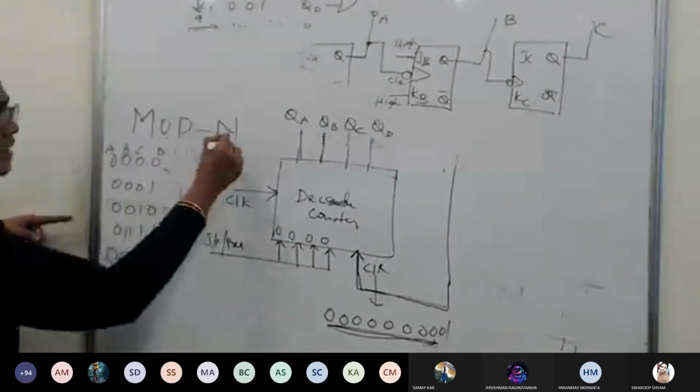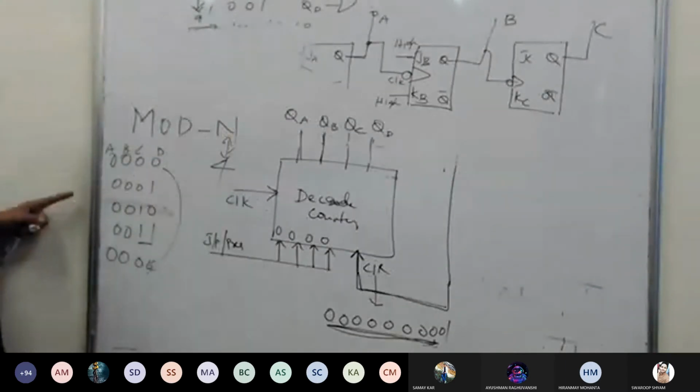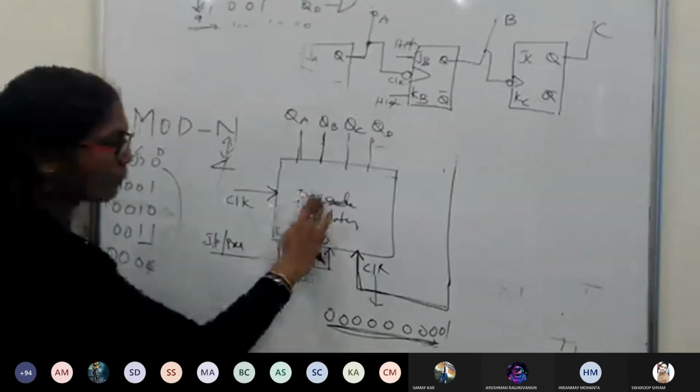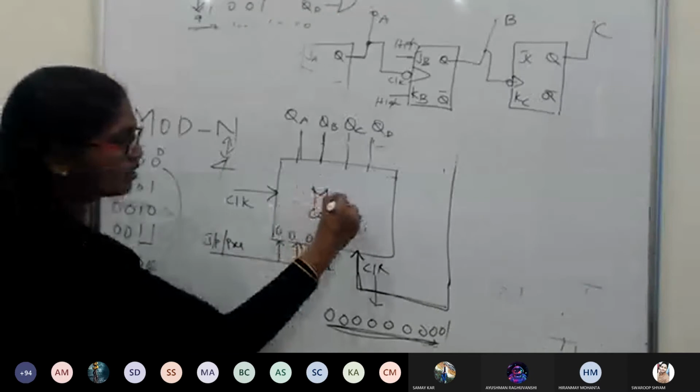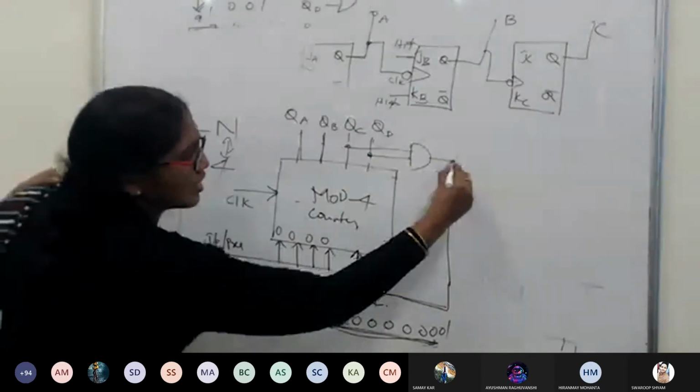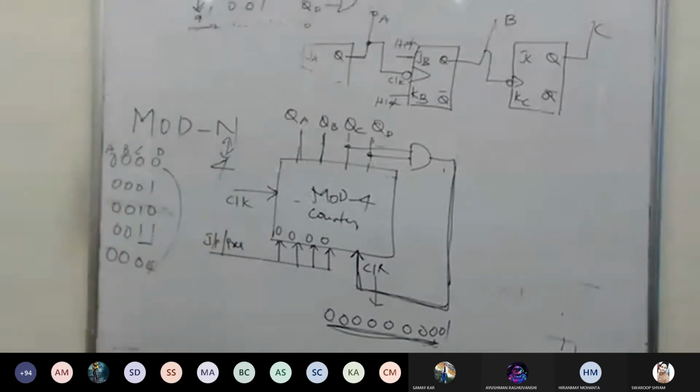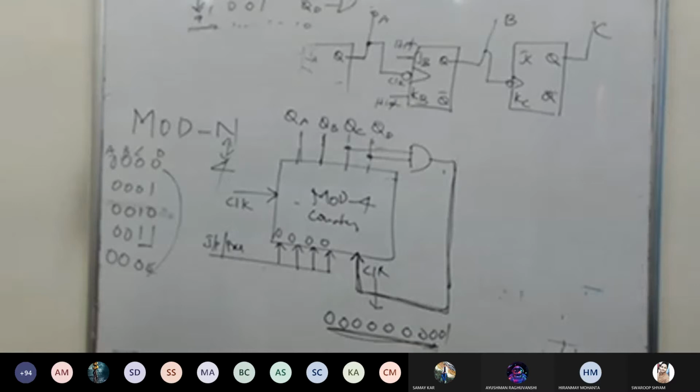Now this one is a modulo 4 count. That means 4 different states can be evolved, and again I can continue the same states. So it becomes a mod 4 counter. If I use some extra gates, then feed it to clear. Did you see now why I called this a genie? These are the miraculous things happening. Preset, clear, they can run the show like anything.